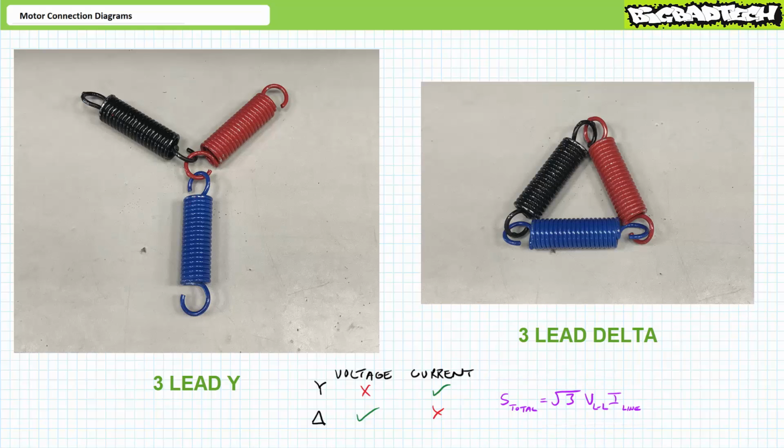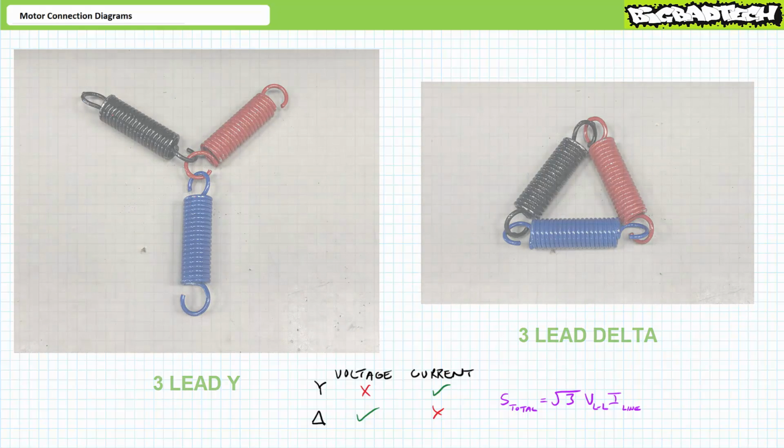Related to today's topic of discussion, motor connection diagrams, you should understand that certain configurations preclude invasive inspection, and some electrical properties aren't as easily obtained as one might think. This being said, line-to-line voltage and line current readings are always an option because they're entirely external to the motor, and the single wattmeter method can be used to calculate apparent power delivered to the motor under inspection, regardless of configuration, Y or delta.